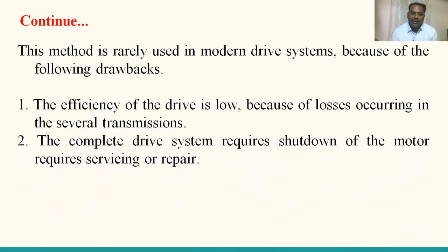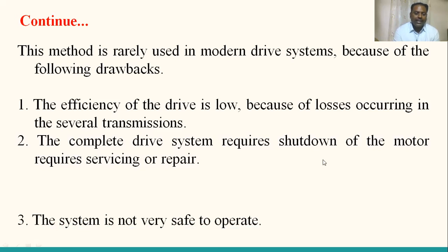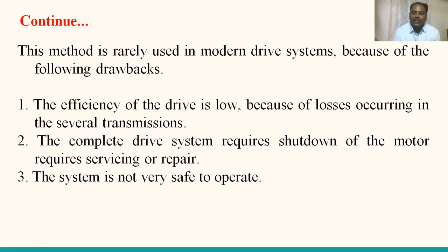So there is one main motor, and according to that main motor, all the other individual motors function. Any trouble in the main motor results in a complete shutdown, and servicing and repair is required. This is another drawback, because everything depends upon the main motor. And similarly, the system is not very safe to operate.